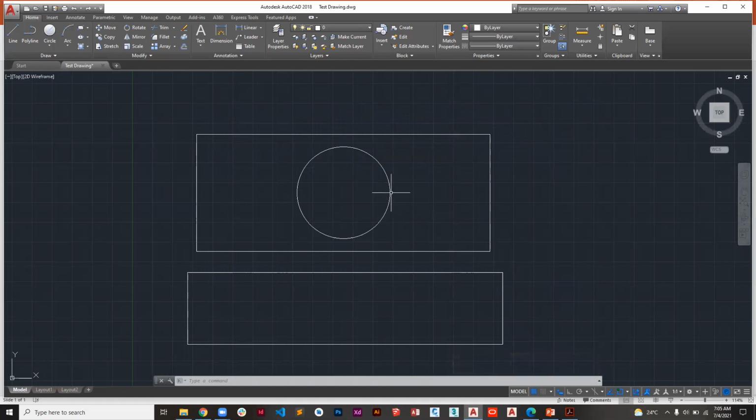So I cannot use the end grip to move the whole line to another place? You can if you first click on it to get the red. For it will attach this other point at the end, so it can't move it. It will just move one point. It doesn't move the whole line.